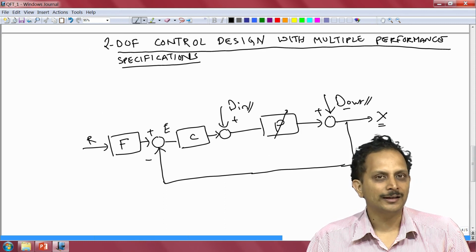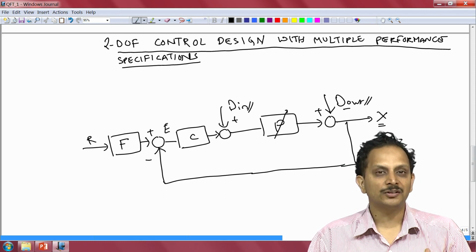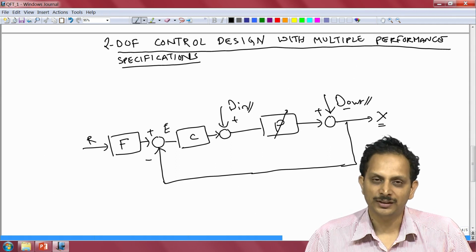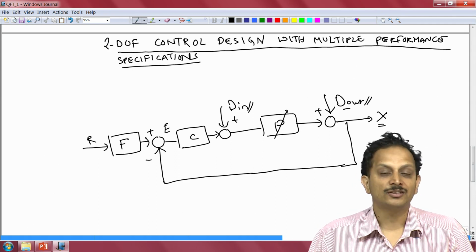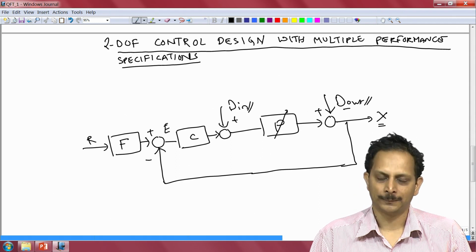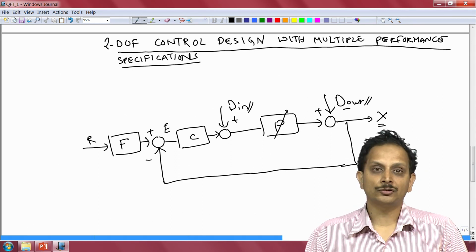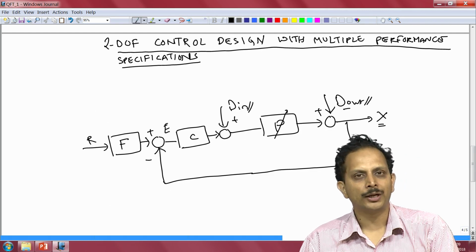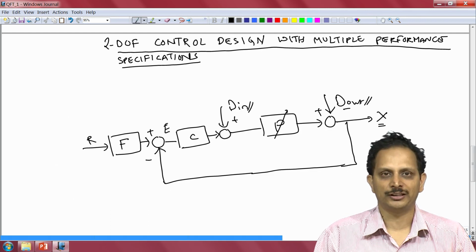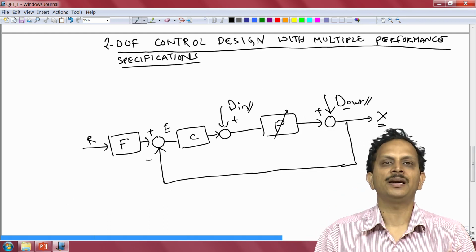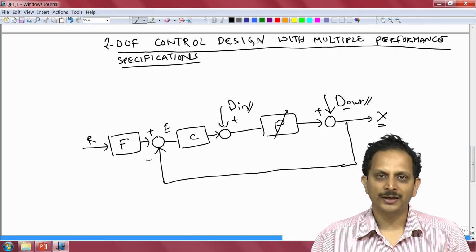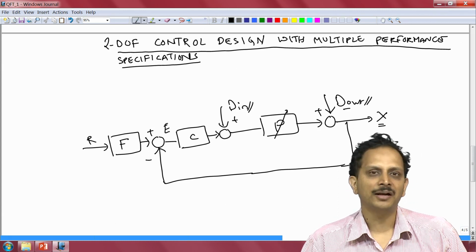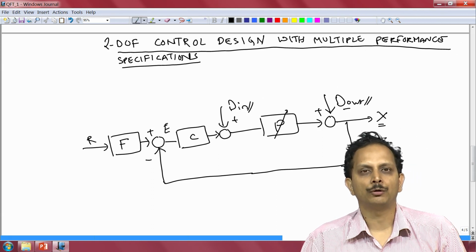It turns out, ironically, that when it comes to representing the constraints imposed on the loop gain by the different performance specifications, the Nyquist plot is actually better than the Bode plot. Though the loop shape itself might be non-intuitive in its appearance, the constraints can be depicted in a transparent and clear manner in a Nyquist plot compared to a Bode plot.